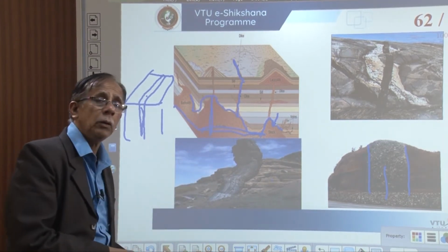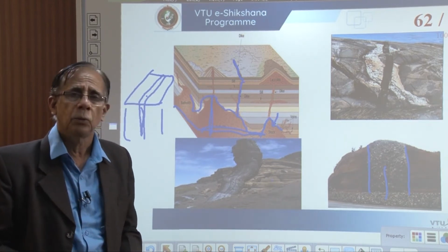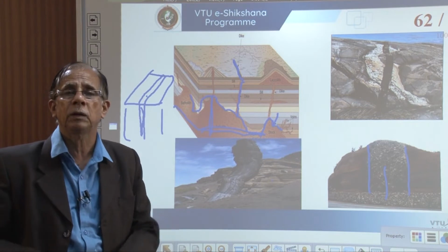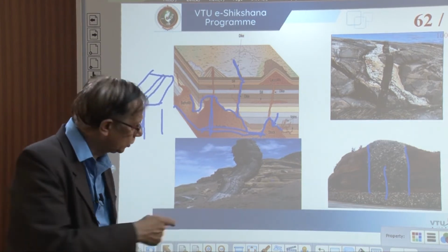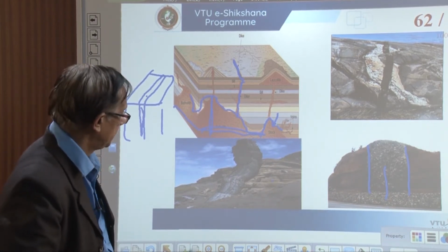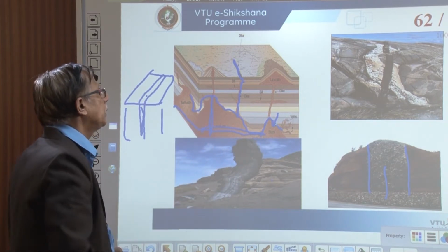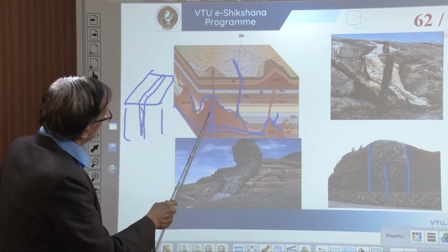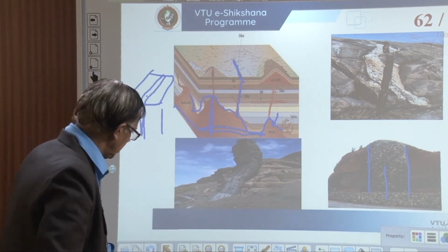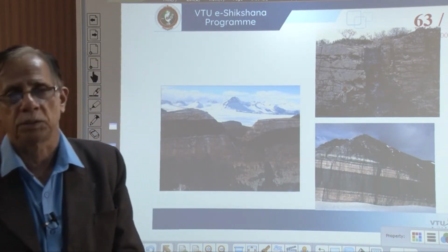Lava flow may not yield a good quality material because of many reasons which we have discussed. They can be glassy, or they may contain a lot of gas cavities in them. I will show you some more slides. Therefore, they are inferior. Rocks can be of smaller quantity but good quality, or moderate quantity but not of good quality. All these are there in nature. We have to decide based on our investigation.